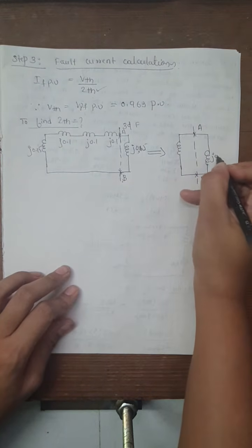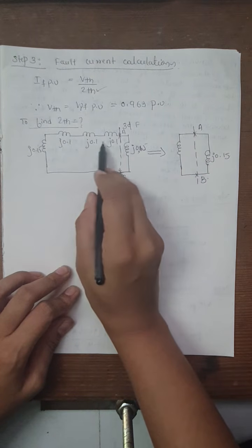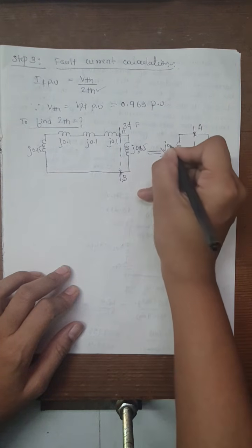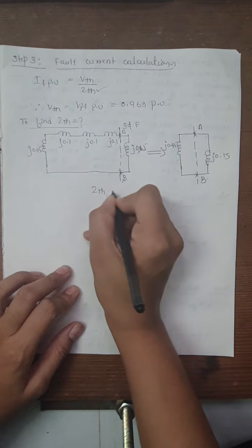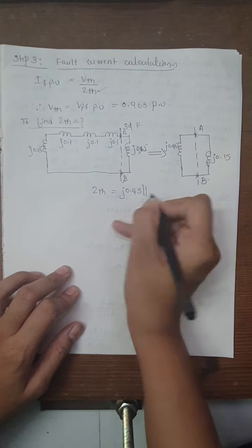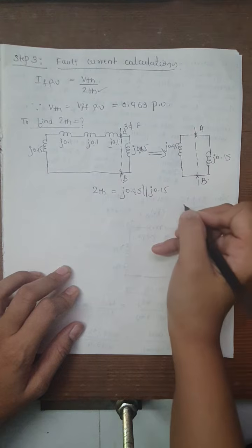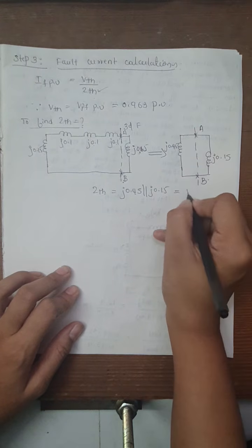So this reactance of the motor is J0.15. So now observe here, adding all these 3 reactances, J0.1, J0.1 and J0.15, we will get J0.45. So in order to find ZTH value, we need to use a parallel formula, that is J0.45 is in parallel with J0.15. So after that we will get the ZTH value as